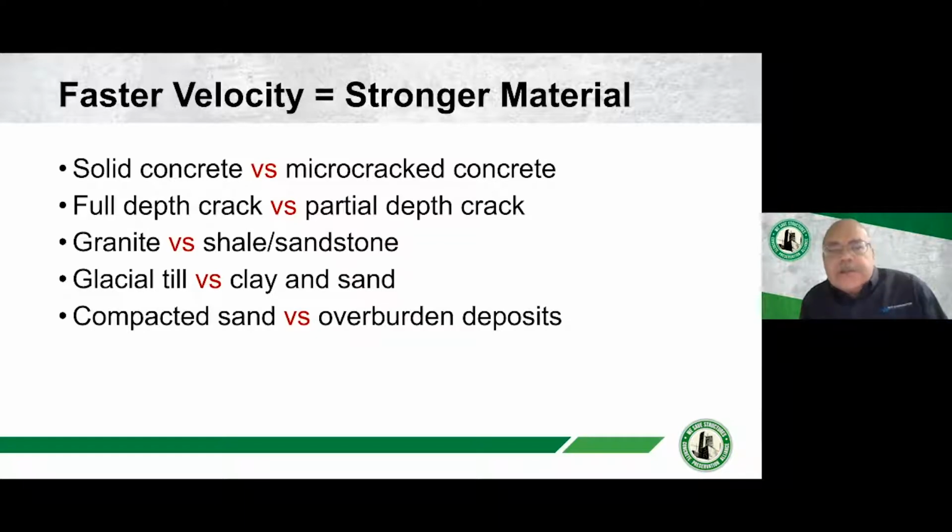So a solid piece of concrete versus concrete that's punky or micro cracked, those velocities are going to go quicker in solid concrete. If there's a crack in the depth of a deck, whether it's a full depth or partial depth crack, we're going to be interpreting how the energy waves propagate around that crack and how fast they go.